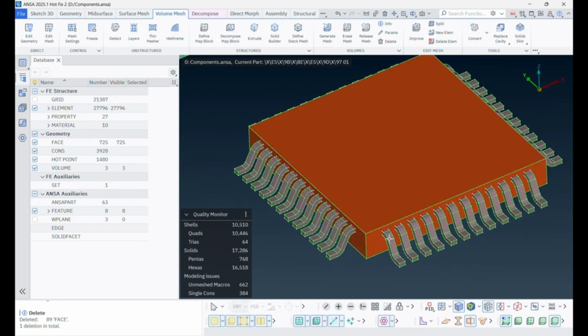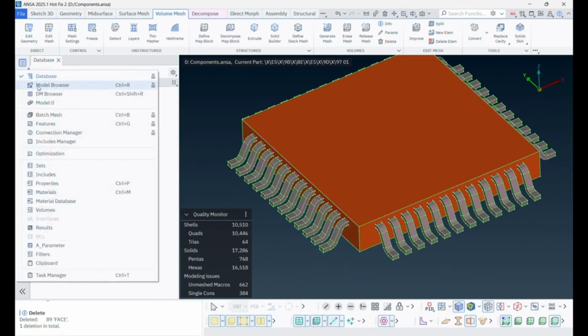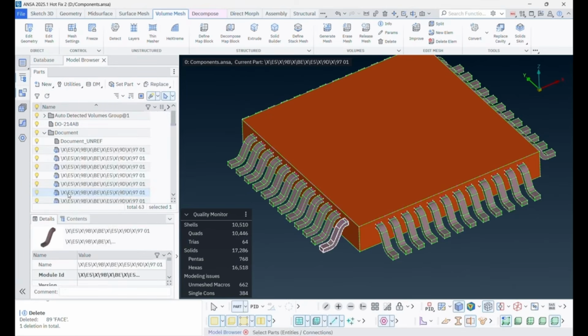The second step is to handle the pin connectivity. It is recommended to select one instance in the model browser, then manually apply fill and plane cut. This step is not only for filling surfaces, but more importantly, for preparing the mesh flow for the following steps.